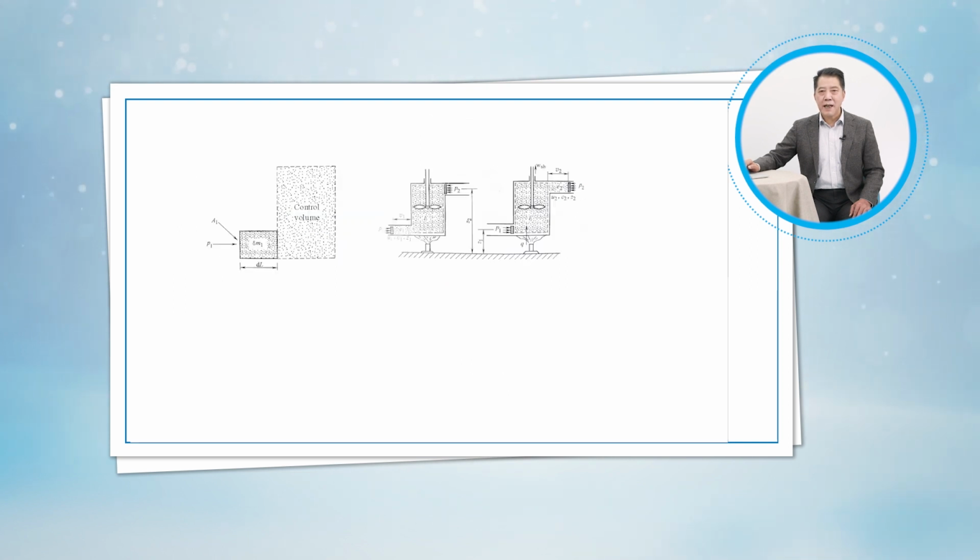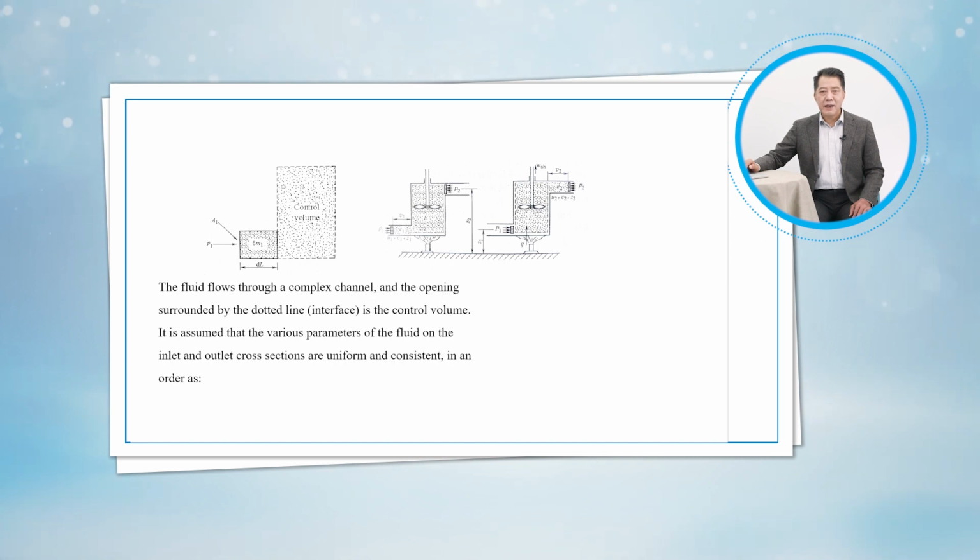The topic of this subtask is about the energy equation of steady flow. The fluid properties at an inlet or exit remain constant during a steady flow process. The properties may, however, be different at different inlets and exits. They may even vary over the cross-section of an inlet or an exit. However, all properties, including the velocity and elevation, must remain constant with time at a fixed point at an inlet or exit. It follows that the mass flow rate of the fluid at an opening must remain constant during a steady flow process.